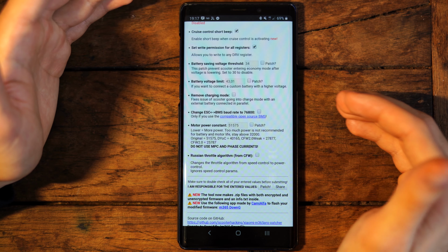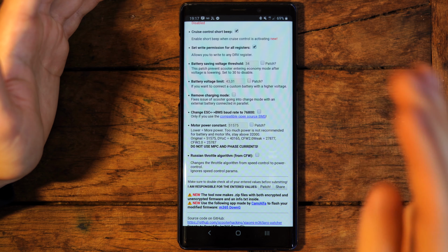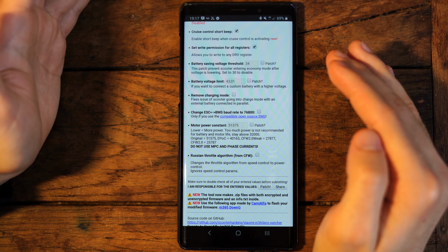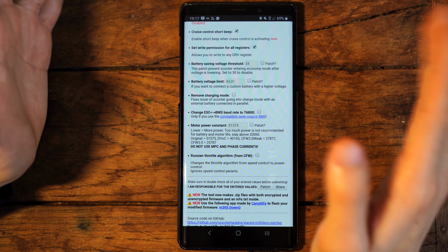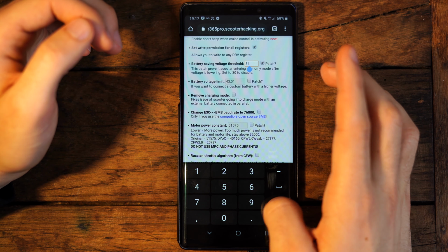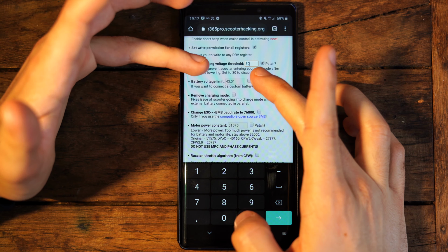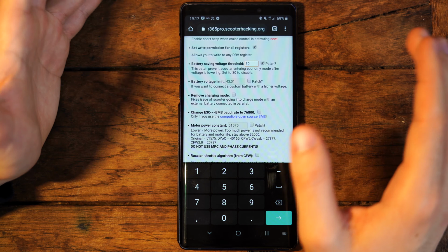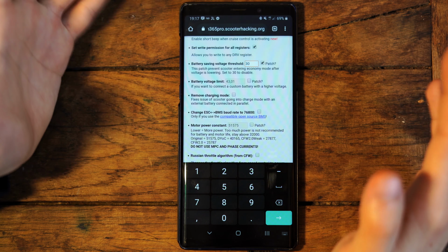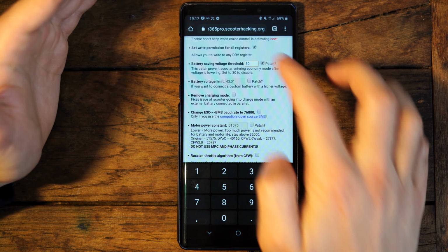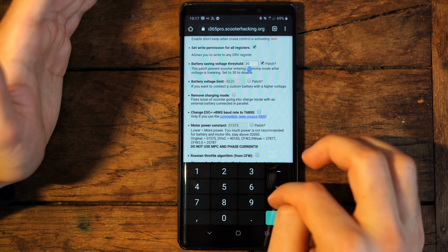If you don't want it to be like this, if you just want to go 35 kilometers per hour all the way through the battery level, you can patch it to be at around 30, for example, because at 30 volts, it won't slow down the scooter even though the voltage is low. But to have a better battery lifetime, it's better to leave it at 34 volts.